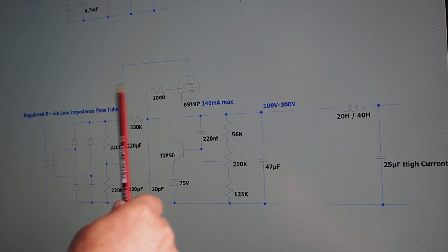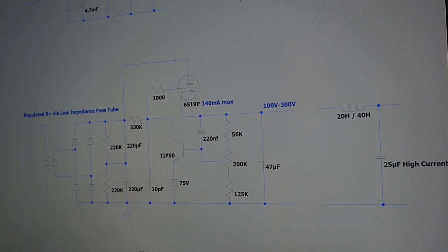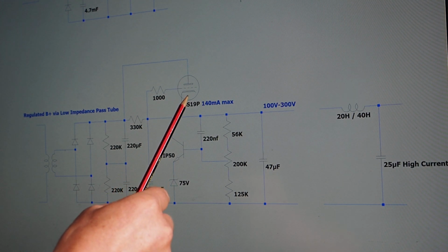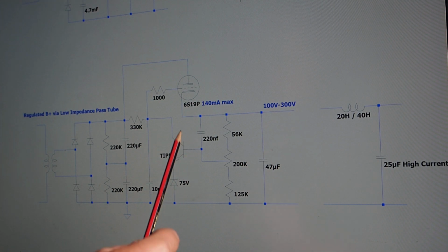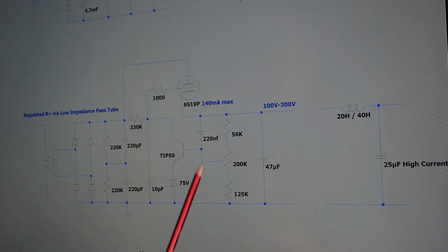As I said, this is not perfect. Don't think this is perfect. I know that a lot of people designing single-ended amps will actually use the tube somewhere here, so it will create a path to the ground, by shunt, not by pass. And that's of course a very good approach. It's probably a better approach. However, as said, if you apply this one well within its limitations, this works well.